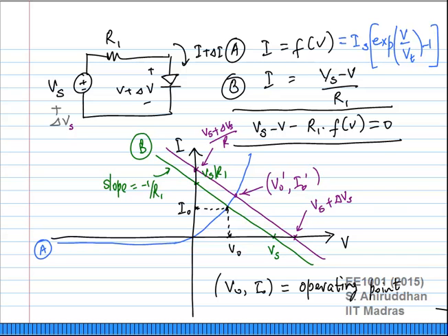Unfortunately, there is no other way than to solve the nonlinear equation to get the solution. If you have a nonlinear element, we don't have any way out of that. There are many ways to do this using simulation. If you want to do it by hand, you can try some kind of iteration. The Newton-Raphson method can also be done by hand. You can try it graphically, which is what we did in class last time. There are many ways to solve this network.